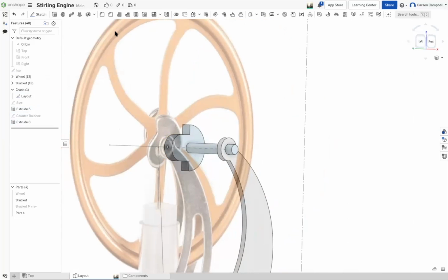The reason why I'm making this thick, Carson, is because you're going to press fit pins inside of this thing. If we make it 2, it's not going to last. So we got to make these counterbalances thick enough that when we push these shaft pieces into them, they stay in there. The thinner we make that counterbalance, the less they're going to want to press fit in, okay?